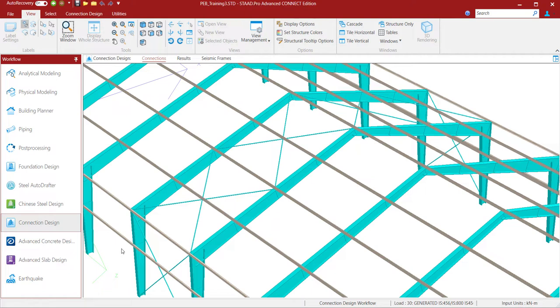If you want to establish the link through its centroid, then also you can define there. By default, in the normal analytical interface, all the connections are through its shear center. So in the physical modeler interface, you can have the choice to define the exact location through which the connection between these two components is to be established.